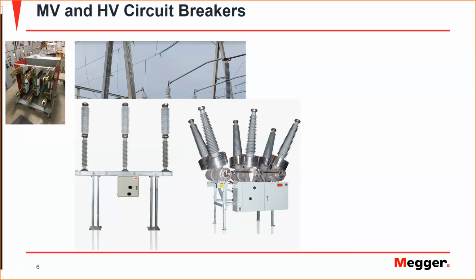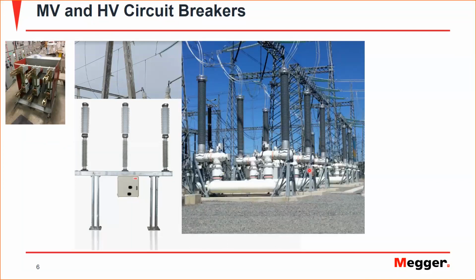Then we have some kind of hybrid circuit breakers, which is basically a combination of both AIS and GIS systems. These kinds of circuit breakers have both the compactness of GIS systems, for example, for their disconnectors and some earthing systems, and the, I would say, cost effectiveness of the non-GIS or AIS systems.